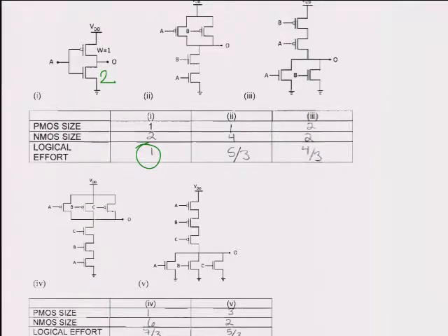That's always the standard. Logical effort of the inverter, 1. The only thing that really changes is that you inverted everything. If you look at this NAND gate here, we now have 2 PMOS in series. This has to be 4, 4. This has to be 1, 1. You get 5 as the overall input capacity, so your logical effort becomes 5/3.